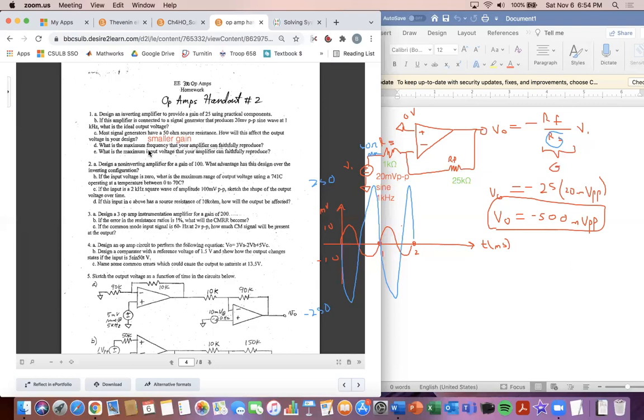Okay, here we go. Okay, so how you do number D is you have to think about the gain bandwidth. And so the max frequency it can reproduce is the gain bandwidth ratio. And if you guys remember that, it's typically 700 kilohertz. And that's for the 741 op amp. Okay, and so for part D, we know the gain is going to be, okay, sorry, I'm just going to put this right here for number 4.